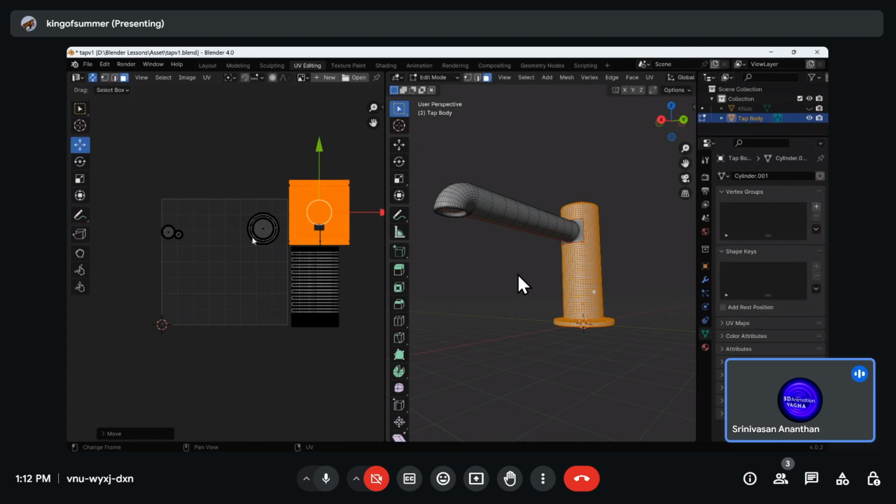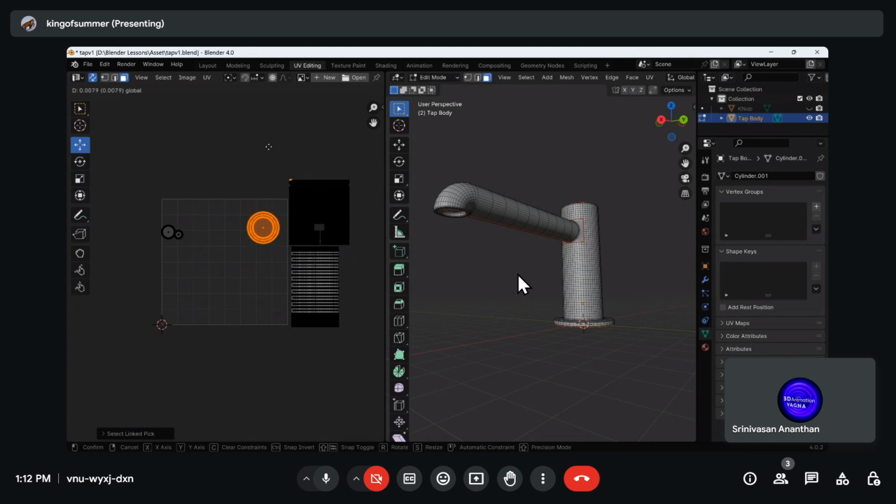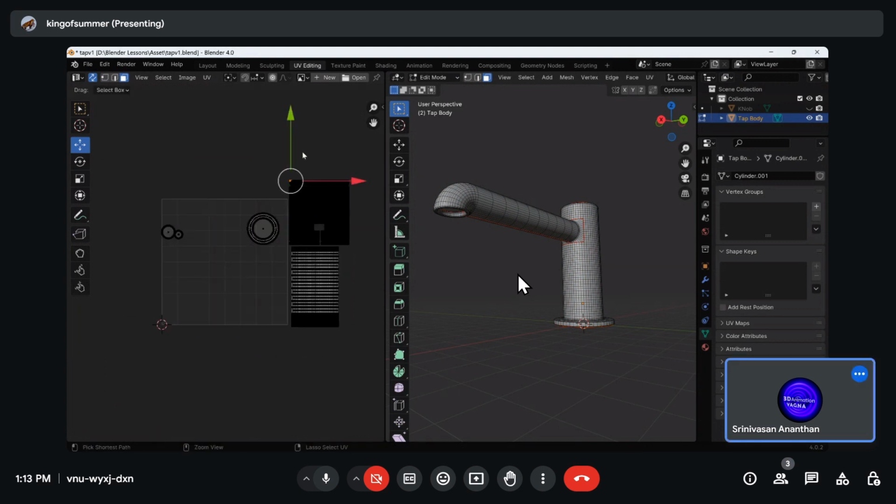Now these circles also, just select them. We have to deselect and then... no, no. Undo. You have selected something else. Press L on that and then move it to the right side. Okay, fine. So we have to empty this UV space. This also. Every island should have a gap between them so that they are not overlapping. Selection will be easy, to select them and move them.